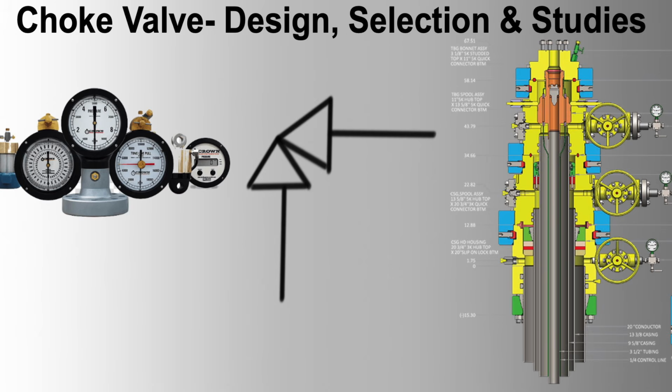5. Well testing operations. Type positive choke valves. Scenario: well testing where precise, discrete flow rates are needed. Advantage: precise control over flow rates enhances the accuracy of test results. Disadvantage: manual adjustment of orifices can cause operational downtime.